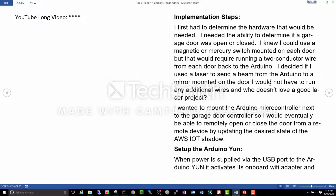My intention is to mount the Arduino microcontroller next to the garage door controller, shine the laser beam from it to a mirror mounted on the doors, and reflect that laser beam back to a receiver on the Arduino. When that beam is continuous and reflected, the door is closed. When the beam is interrupted by the door being open, the door is open and it writes an update to the AWS IoT shadow.